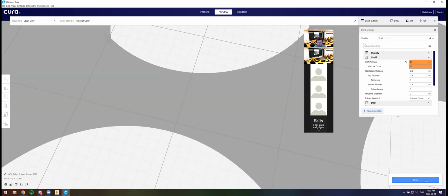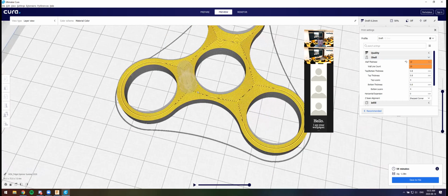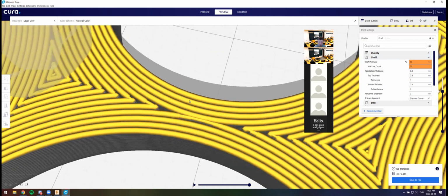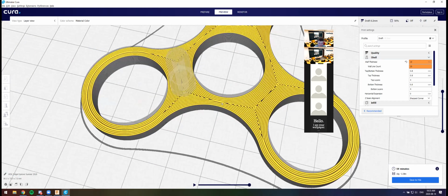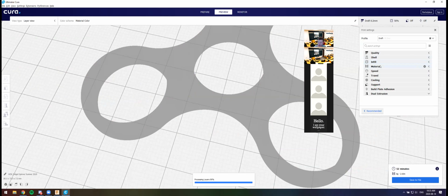I don't know, look at this. If I do like a 10 millimeter wall thickness, everything will just be filled with walls. But then, would that mean it's super strong? Kind of, and not really though. It's better to have 100% infill than this kind of wall thickness, because if you can see, the patterning on the plastic isn't as strong. Okay, let's talk about the next thing, material.